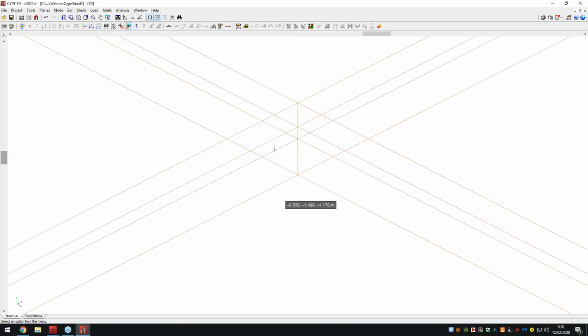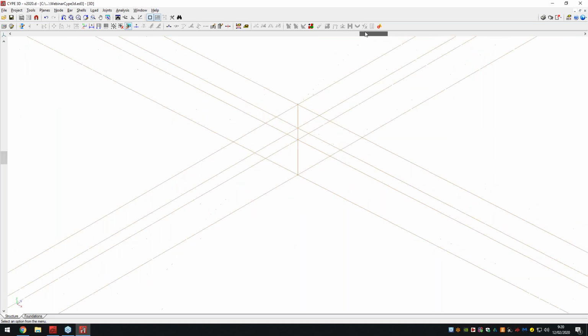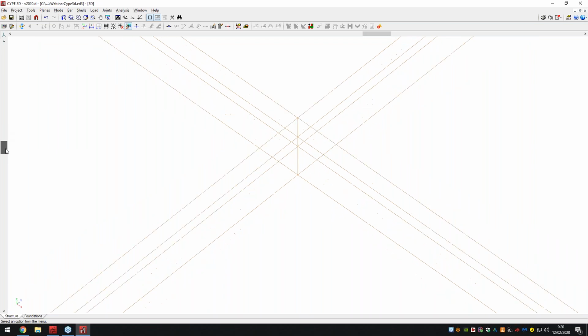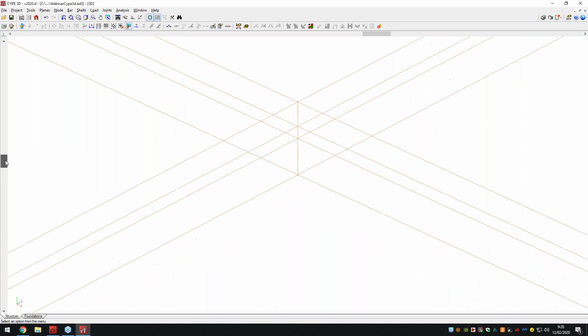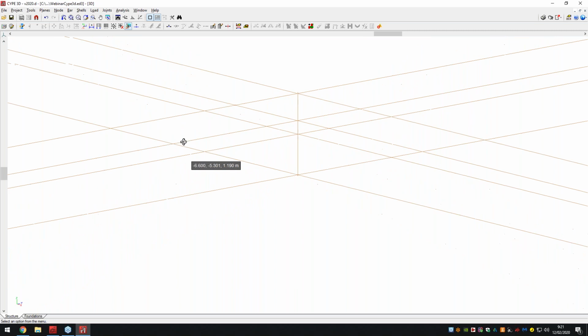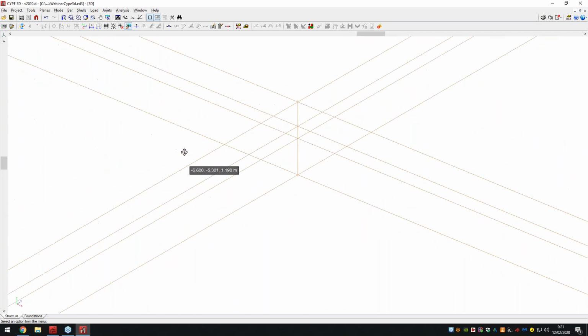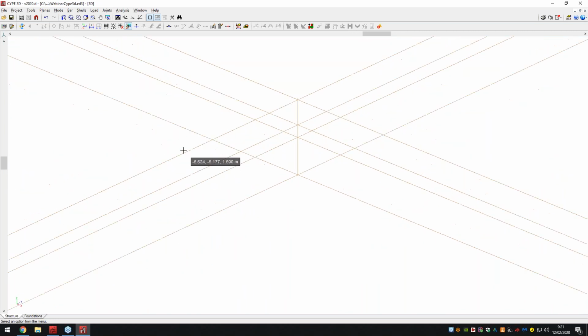So upon inserting that, you can see here that the program automatically, through the view, separates those different sections for me. Now, of course, I can maneuver around these sections as well using our tab here, using our scroller here, and also in the X and Y direction here as well. I can also do it by learning some shortcuts. So holding the Shift key and my middle scroll button, I can do both at the same time as well.